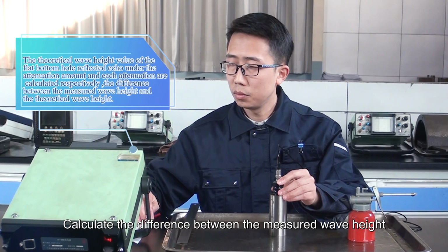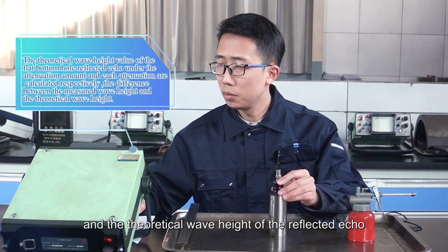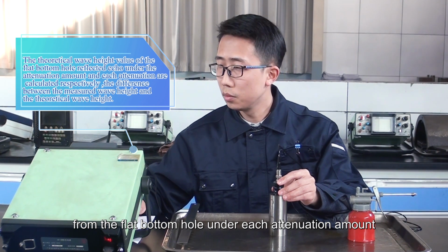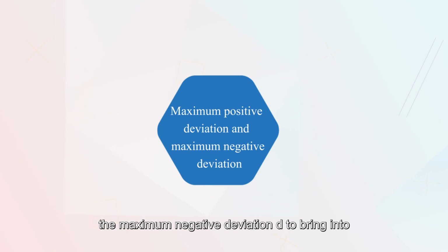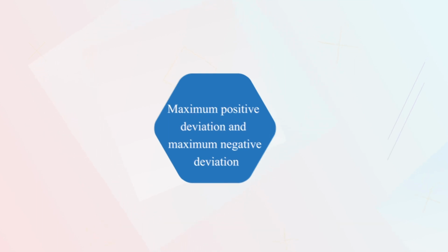Calculate the difference between the measured wave height and the theoretical wave height of the reflected echo from the flat bottom hole under each attenuation amount, and select the maximum positive deviation d+ and the maximum negative deviation d- to bring into the calculation formula.